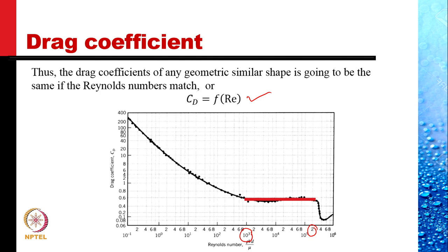is of great importance. In fact, you would see tables in handbooks for drag coefficients where the Reynolds number is not mentioned. The drag coefficient for a sphere in laminar flow is given as about 0.6, for a flat disk about 1.1, and so on.